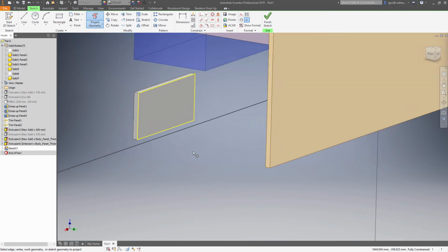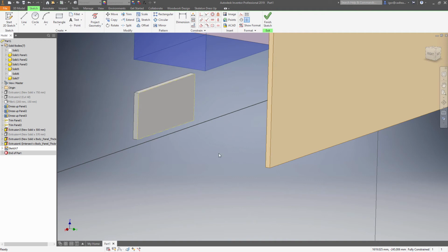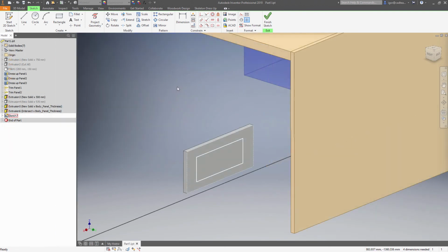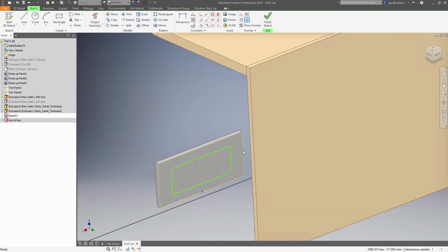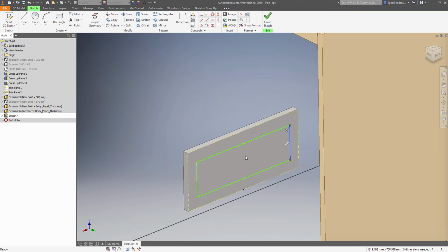Use the back side of a drawer to draw the drawer box. Draw a rectangle first, then use a constraint to position it symmetrically along the vertical line. Now connect the rectangle with the sides of the facade. And define the box offset from the top and the bottom.